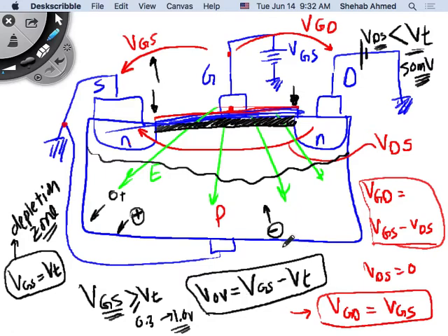I think we agreed now that our interest is in the thickness of the channel. Okay, without the VDS, the thickness of the channel is controlled by the overdrive voltage. The overdrive voltage is a voltage that is beyond VT. So only if the gate voltage here is beyond VT am I going to affect the thickness of the channel, right? Now, with this new situation, let's go back to this important equation that I said before, this one here, VGD. So VGS is not going to change, right? Does VGS change when I put VDS?